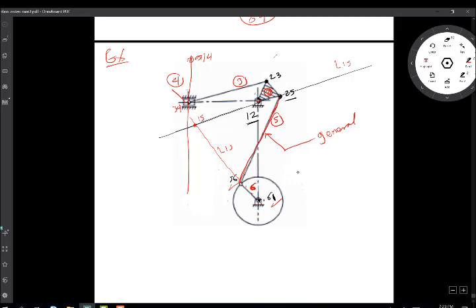Similar to this is link number 3 type thing. So if you want the velocity omega 3 for link number 3, it would be as simple as, for example, to extend. Realize now that you have 2,3 at this end, 1,2, so you can extend this, both ends will give you a locus for 1,3. This is locus for 1,3, and this end here, this is 3,4, and 1,4 at infinity.